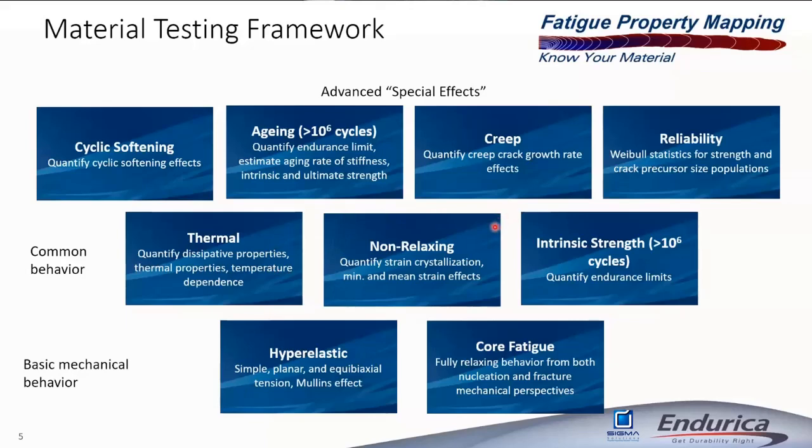Under conditions where you have a mean stress, or what we call a non-relaxing cycle, think of an engine mount where you have a static load on which is superimposed dynamic cycles. Some rubbers can exhibit an effect called strain crystallization, and it can affect the fatigue life by a factor of 1,000 or 10,000. In that case, it's necessary to characterize the strain crystallization effect and include that as part